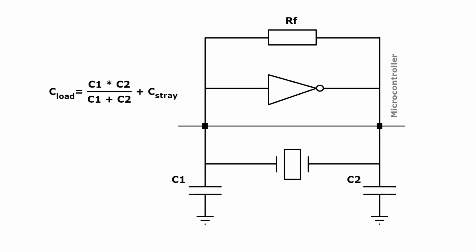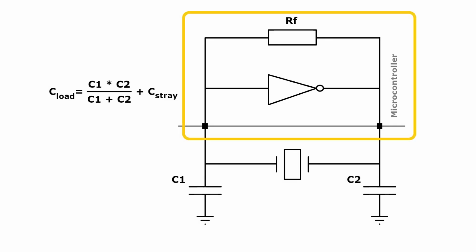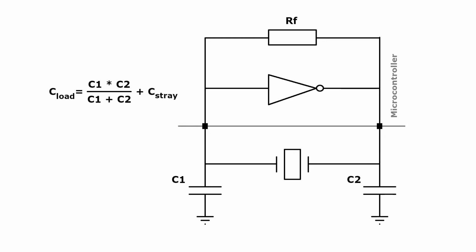Before we look at the actual hardware with the crystal, we should first determine what is the value of the components that go along with it. So if you look at this diagram, and if you remember, the crystal, together with two load capacitors and the circuitry which is already inside the microcontroller, is what forms the oscillator that generates the clock for the microcontroller. So we do have to provide not just the crystal, but the two load capacitors. So what is the value for those load capacitors?